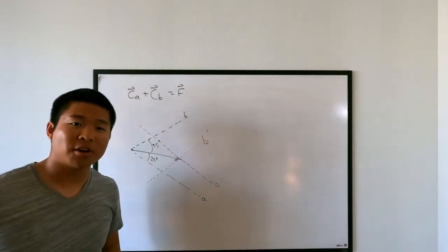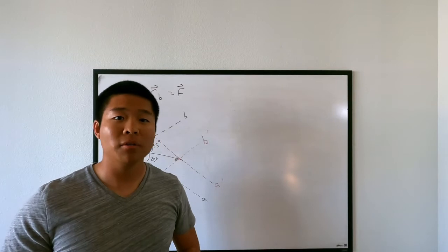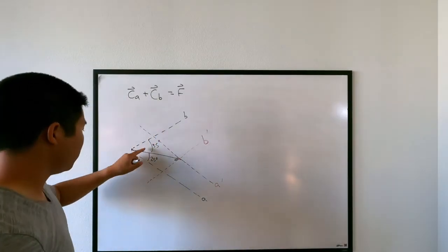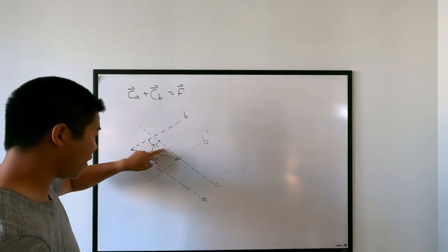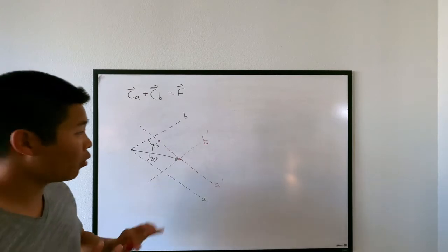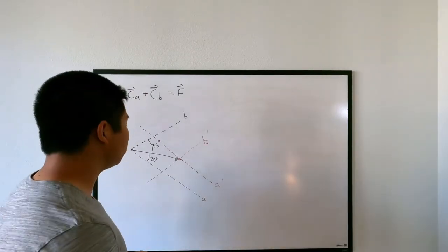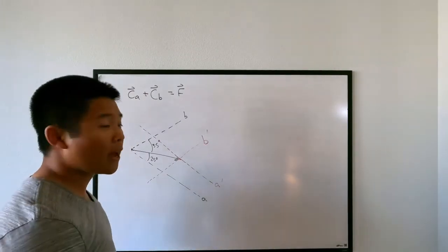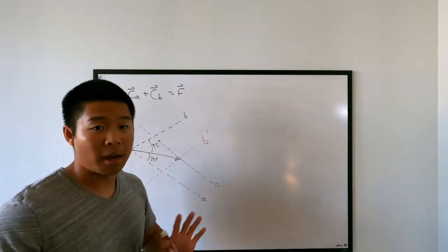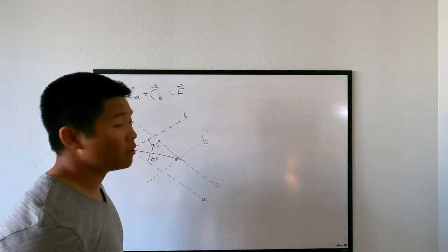But it's interesting that this is called the parallelogram rule because it turns out that we don't actually need the entire parallelogram. We only need half of it, either the top half or the bottom half. What I always like to do, and I always recommend this to everyone when they do a parallelogram rule problem, is that they take whichever piece they use, top or bottom, it does not matter, and they redraw it.